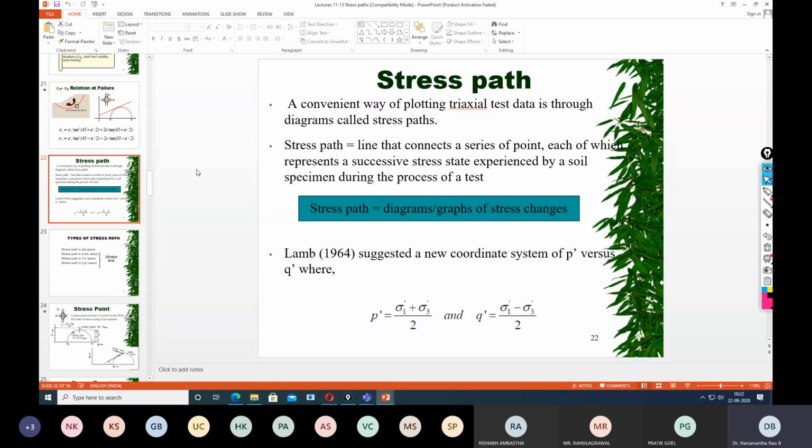That is in case of sandy soil. Let us take the clayey soil. So initially there is elastic settlement, then followed by the consolidation. Since the consolidation is a slow process, the shear stress imposition on the soil is very slow. Since the soil requires a sufficient amount of time for the settlement, it takes a little amount of time for the failure plane to develop. But if there is no settlement, there is no shear stress on the soil.